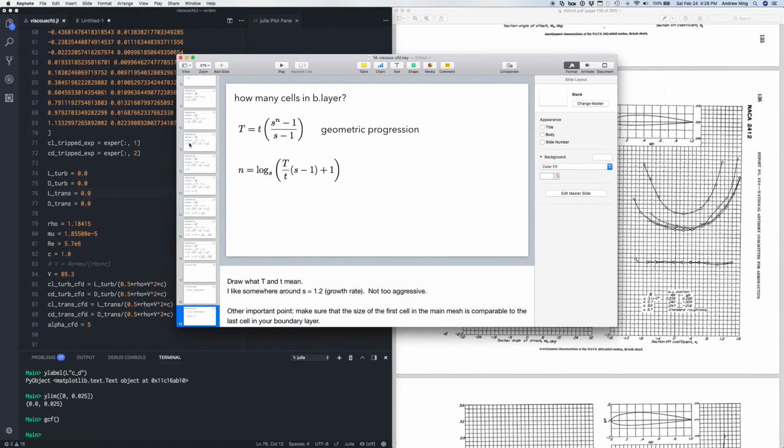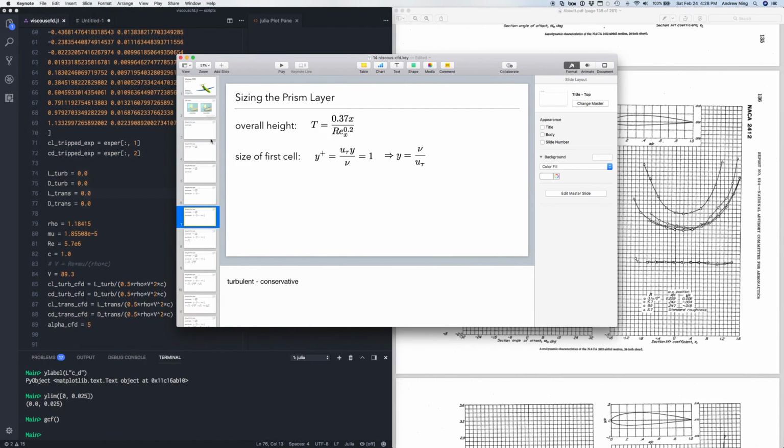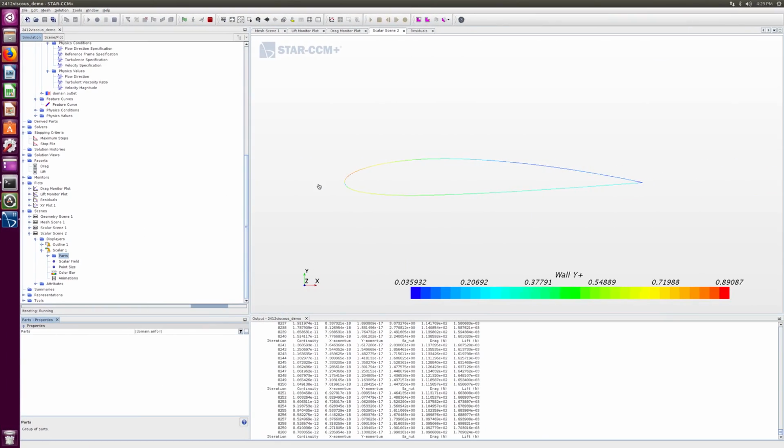And if we go back and look at our definition for Y plus, it has the friction velocity in the numerator, which is proportional to our skin friction, our shear stress, which of course is proportional to the skin friction coefficient. So because that's in the numerator, Y plus is going to be much bigger where that skin friction or the shear stress is really high. It's still rising, but I'm in the neighborhood of 1, so this is looking pretty good.